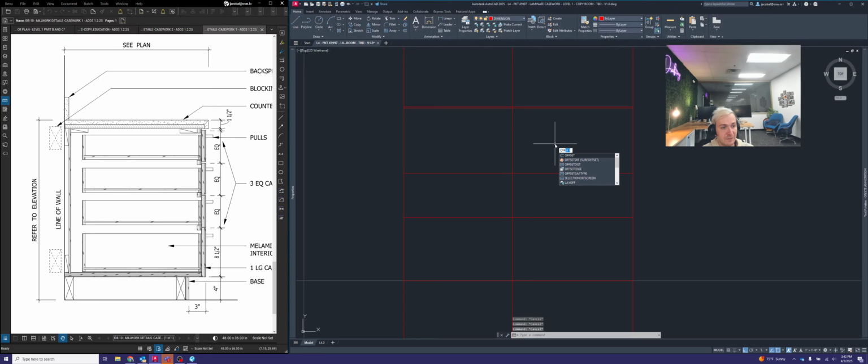So we're going to use our scale factor of 1/2 inch equals a foot. Going back to our measurements toolbar here, it looks like we're already set to that. So 1/2 inch equals a foot. Change our scaling to 1/16 of an inch, so that way our precision is set a little bit greater than what we had before.